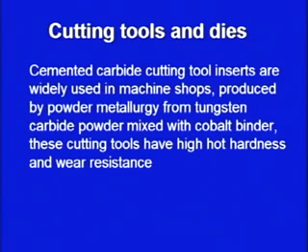So, what is hot hardness? During the machining operation, the temperature rises substantially. So, the tool material should retain its hardness at that elevated temperature. The temperature may go up to a level depending upon the combination of the tool material and the work material. So, the material of the tool should be such that it can withstand the high temperature generated during the cutting operation. So, these cutting tools made of cemented carbide have this property of hot hardness and wear resistance. And how are these cutting tools made? These cutting tools are made by the process of powder metallurgy in which cobalt acts as the binder.